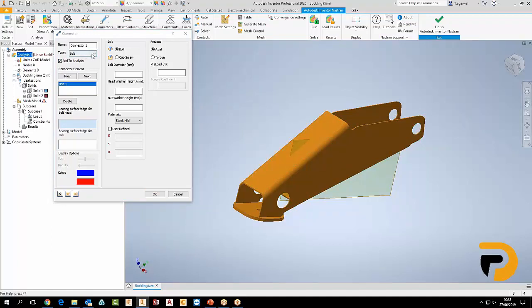Yeah, this goes back to the point we made earlier, that we can simplify the simulation by reducing the connections. We don't need that information. We can predetermine that by using the Nastran connectors here. And Tarun's about to show you how we're going to simulate where this component pivots along its back there, and there's a shaft. So that's why he's going to use this connector option here.